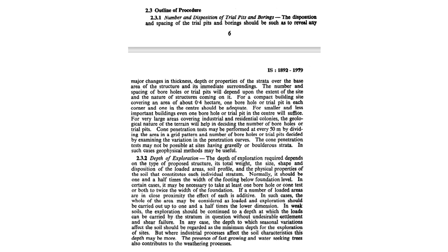Okay, so the idea is that you should be able to understand the soil profile beneath those load bearing parts. Okay, so that is why I said it would be nice if you can take boreholes beneath all columns or beneath all those heavily loaded structures which are identified. And otherwise, we'll see how it is fixed.